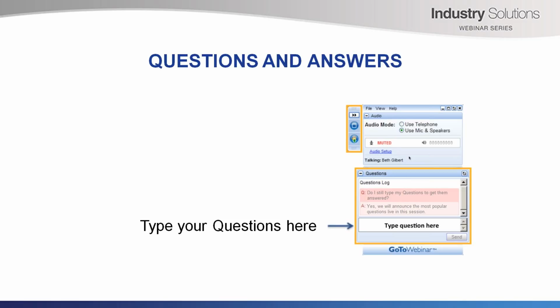Sure. I think we had a comment through from someone in our New South Wales team, in response to this, that just adds that those attributes are not needed for Solibri, but for Navisworks, that information isn't calculated. Do you have anything you want to add to that? Again, this comes into different packages. I would say Solibri probably works out some of those, if it can, from some of the objects you send across, whereas Navisworks can't. So in that case, for Navisworks, you would run the attribute manipulator to put those properties on there beforehand.